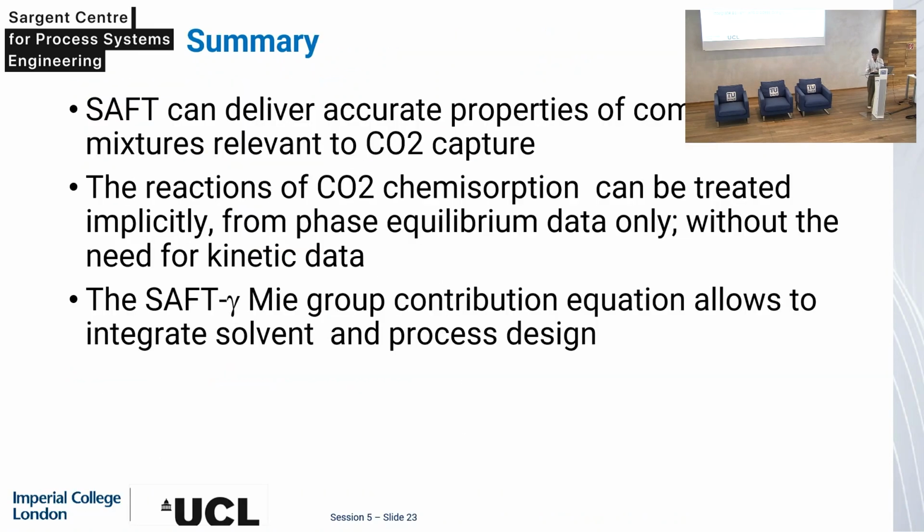Okay. So I realize it was a lot of information very quickly, but I hope I've given you an idea of how SAFT can deliver accurate properties of complex mixtures relevant to CO2 capture, and that, importantly for us, the reactions of chemisorption can be treated implicitly from phase equilibrium data only. We do not need kinetic data, and this allows us to explore solvents, okay? And that moving to a group contribution approach allows us to integrate these approaches to deliver solvent and process design. Okay, with apologies for...